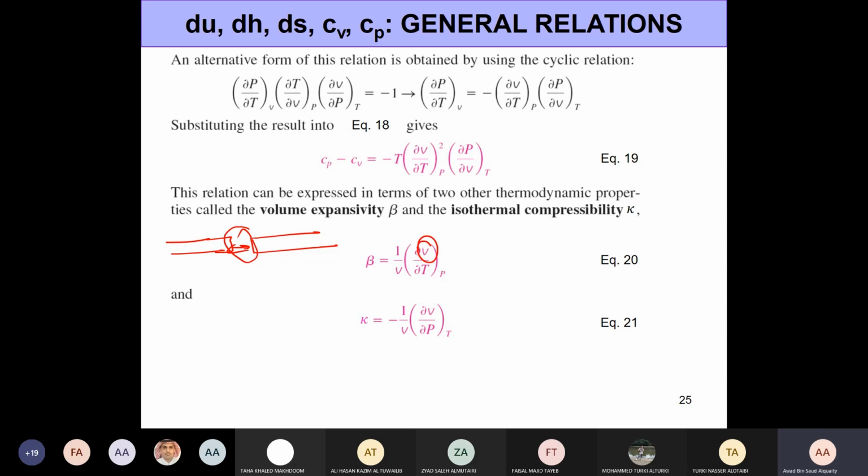You want to allow for the expansion, but at the same time you want this gap to be small. So you select a substance whose beta value is small. We know the temperature changes are going to happen, and we accept that specific volume is going to change, but we are looking for things with very small changes in specific volume. With very small changes, you can keep the tracks close to each other, and yes, they're going to expand and contract, but they will still be fine. They'll not put any stress on each other, and they'll continue to operate efficiently.